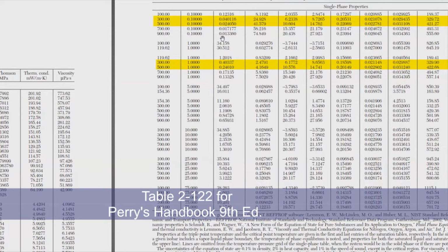If you haven't heard of double interpolation, the first one is that we are interpolating between the values at a fixed pressure, where we'll be using the film temperature here. So we'll be able to find the values at the film temperature at 0.1 megapascals. We'll be doing the same thing for this section here where there is a higher pressure.